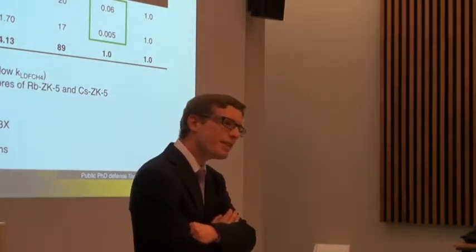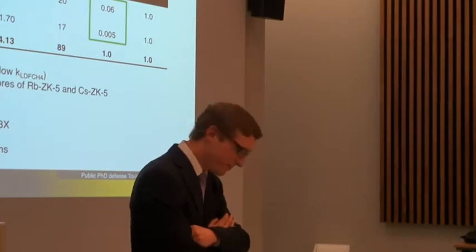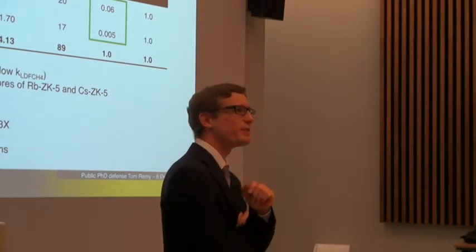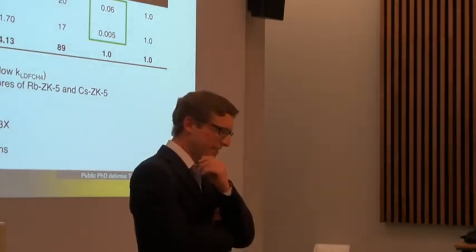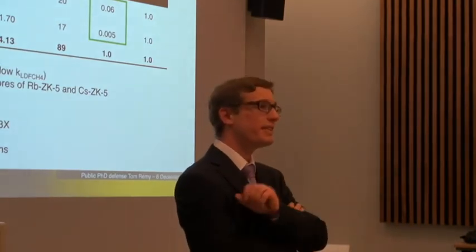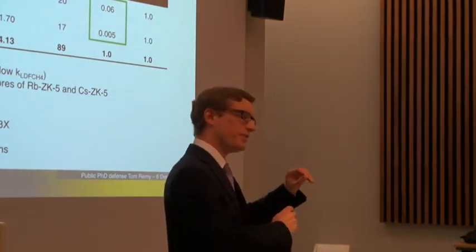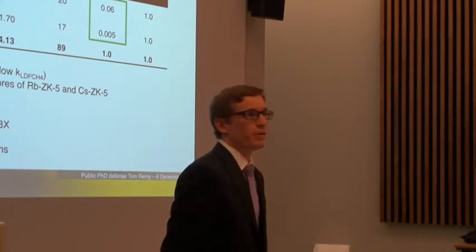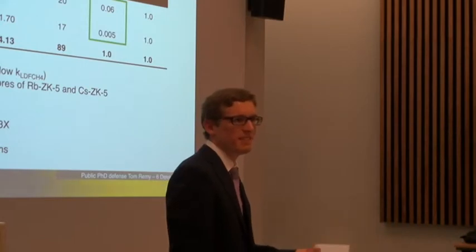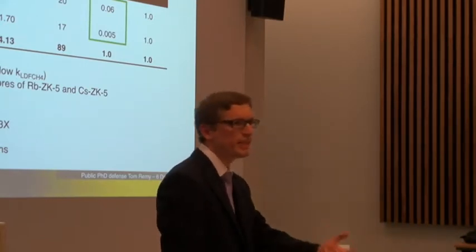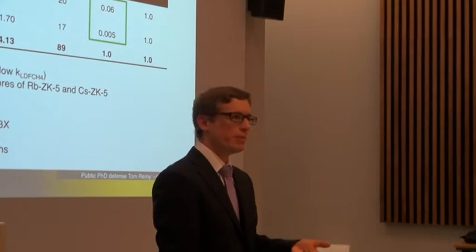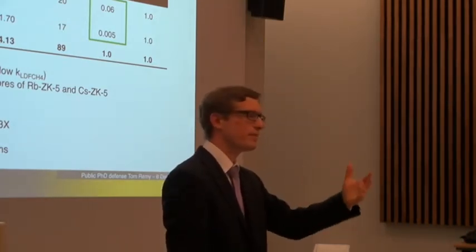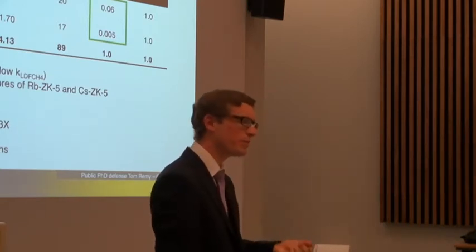I think it's already there. Isn't there a company, Molecular Gate, that has been bought by another company? You should know it. And they work with titanosilicate, and there it's a kinetic separation. It means that the CO2 goes through the material and the methane doesn't go in, and as such you separate them. So the materials to beat the standard chemical absorption are already there. The big problem is that when your gas comes out of the earth, it's at extremely high pressure, like 50 to 100 bars, somewhere between those values.